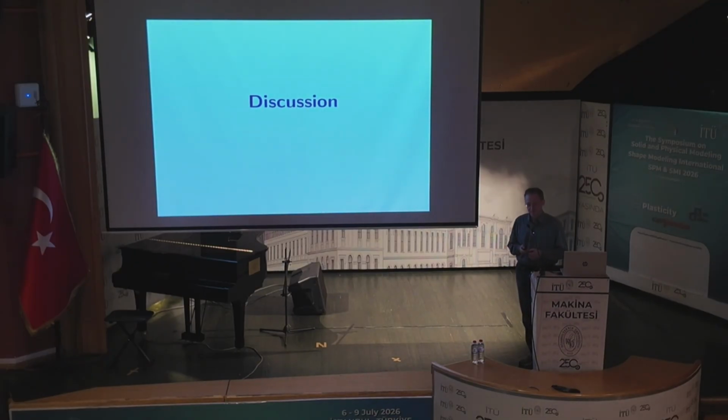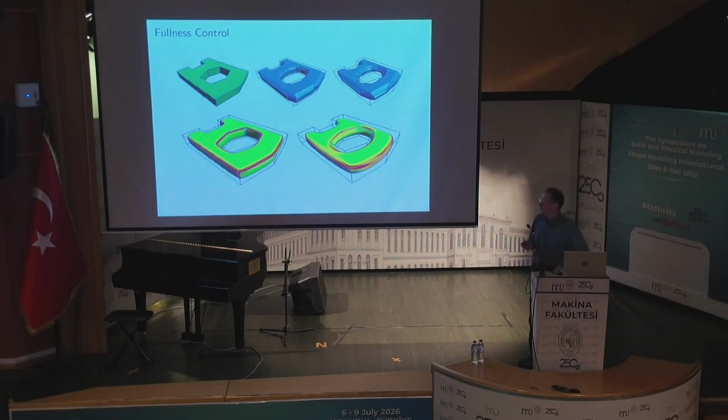And let me give you some details about the construction, which I think are interesting. So first, I have told you that we only use a percentage of the total maximum offset distance. And this is actually a parameter that you can use for controlling the fullness of the patch. So using larger values will give you more smooth corners and edges, while using lower values will give you a more tightly blended appearance.